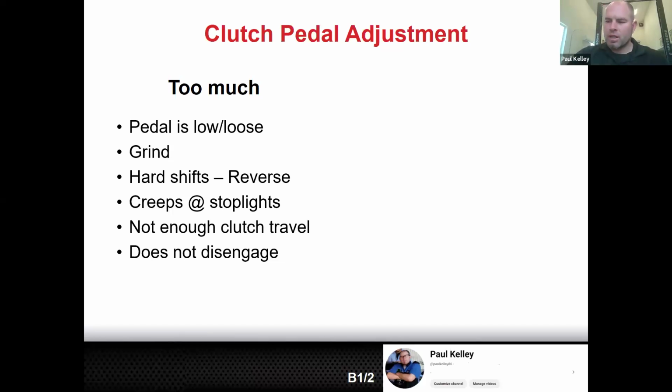So when I talked with the guy who owned the shop, I was like, dude, honestly, that one had me a little sketched out. It's a brand new clutch. How could it be a brand new clutch and that be the problem? And he said, well, look, this is how I diagnosed it. When the clutch was dragging, I went down there with a pry bar and I shoved the pry bar in and threw the clutch fork all the way as far as it would go. And it still was dragging. So if I threw it as far as it would go, it's not the clutch slave or the clutch master or the clutch pedal, none of that stuff. I've already thrown it as far as it can go and it still was dragging. So I don't care anything about the release mechanism. And I was just like, man, this guy's brilliant.